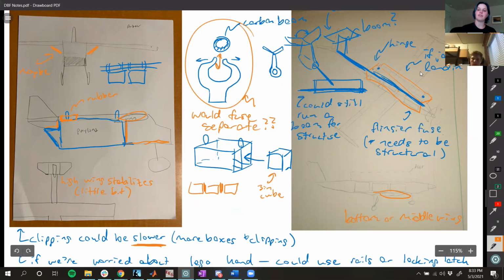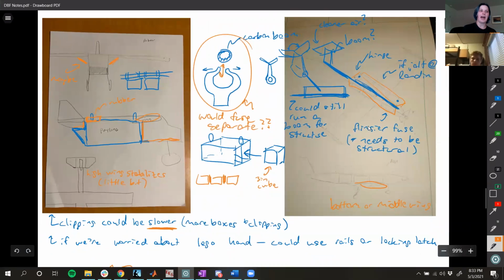So another option is a foam wing that you put fiberglass over. We had some grad students who just wanted to see how fast of a plane they could make. They used a stiff blue foam and then one or two layers of fiberglass, and it didn't even have a spar or anything. It was just the foam and then the structural skin because of the composite. And then it went like 100 miles an hour. It was pretty wild.